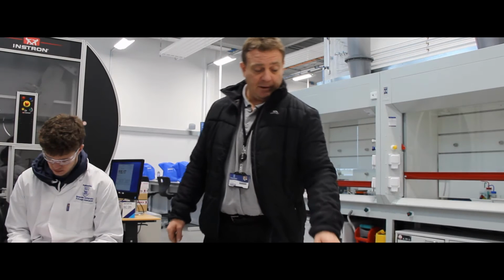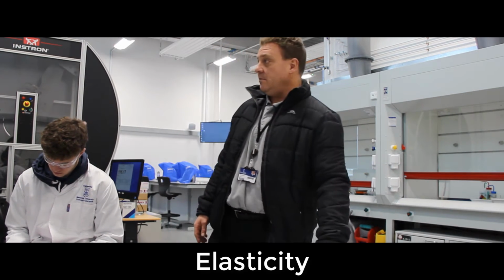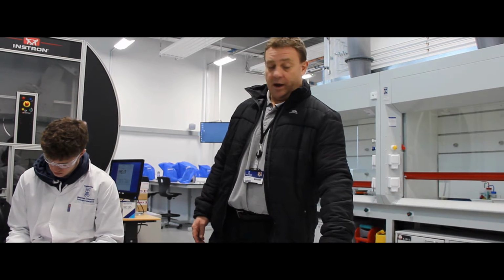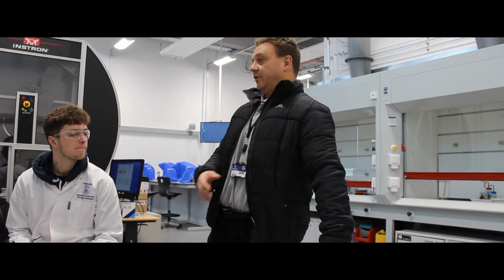The thing to note is that these plane samples are the way you actually get material properties in the first place. So these plane samples give you all the data you need: the elasticity regime, the yield strength, and the ultimate tensile strength. And they're all in that one curve. That was the one curve that we used in the model, a multilinear flow rule, that has everything in it. So you don't have to go off looking for Young's modulus or density or anything for this material. You don't actually know exactly what material it is, but that curve gives you everything you need. And that curve is the one that's being used by the model.